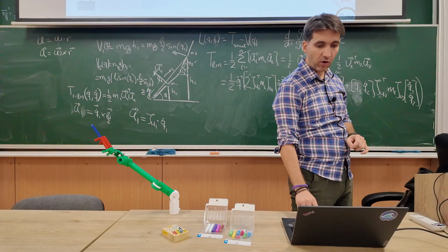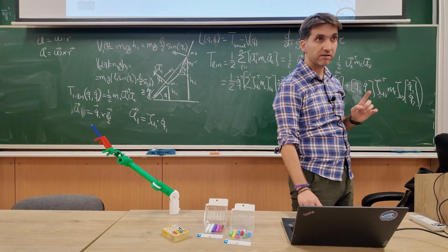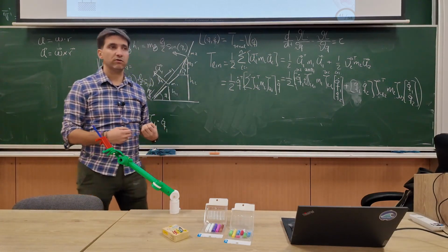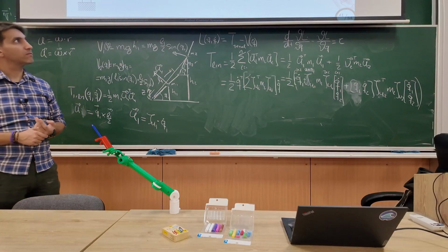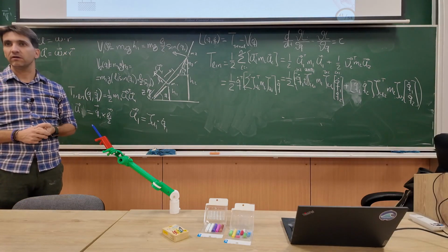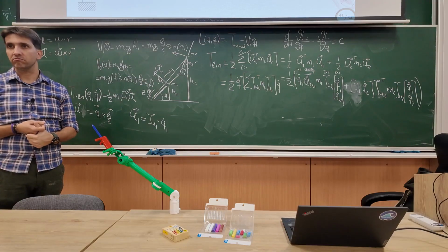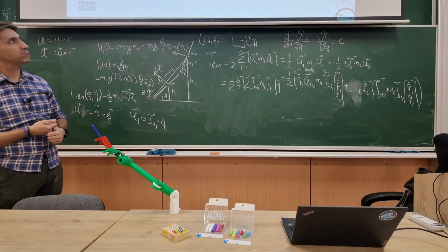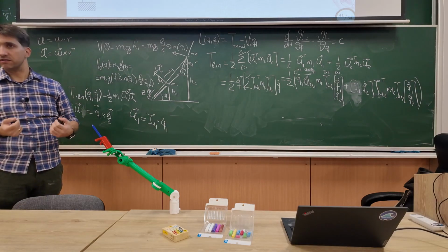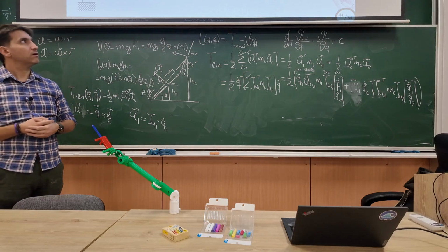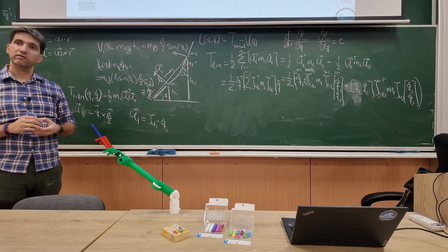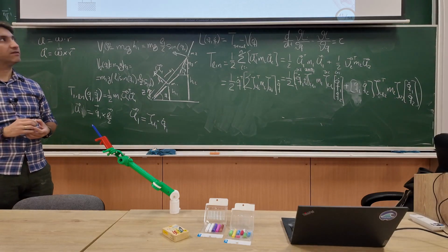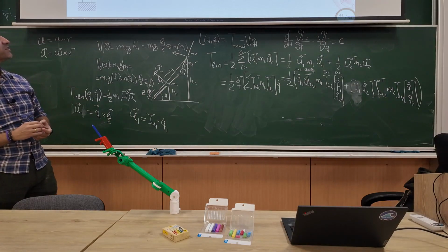So this is basically the overall kinetic energy, the linear kinetic energy for any robot manipulator. What do we need in order to calculate it? What appears there? Joint velocities, which we are controlling, and it's our states. And, sorry? The masses. Joint positions. Why? Very correct. That comes next, but yeah, very correct.